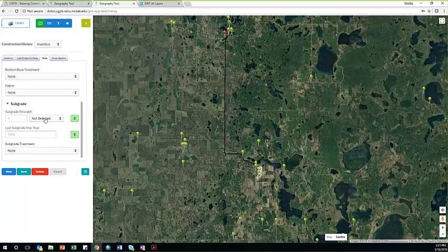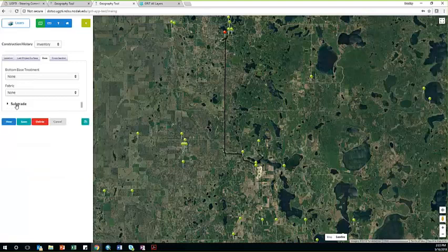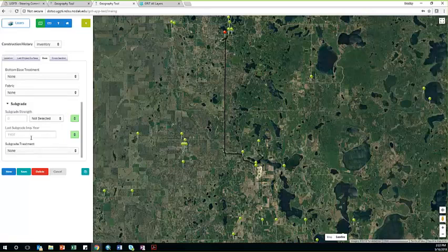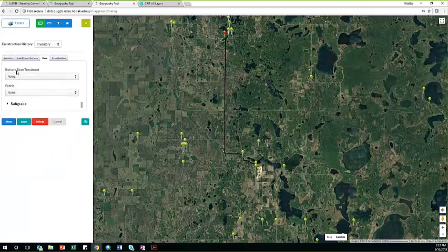We added it in here and I could see maybe it needs a little more of a label, but if you're used to doing resilient modulus for your subgrade strength, you can put that in here and label it, or California bearing ratio, or soil factor, or R value. So you can pick whatever units you're using for your subgrade strength if you're putting one in. And then of course the year, if there was a subgrade improvement out there, the year that happened, and then any subgrade treatment, cement or fly ash or whatever else. So that's your base information.